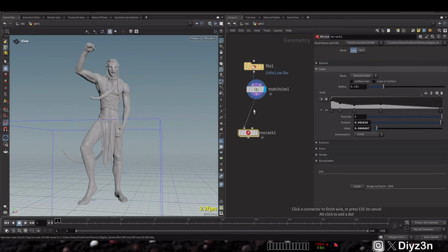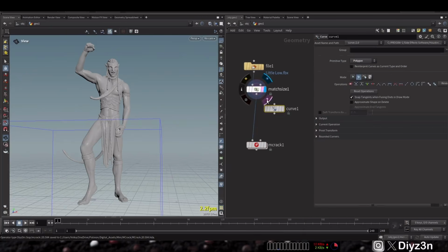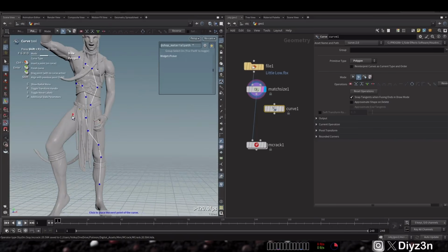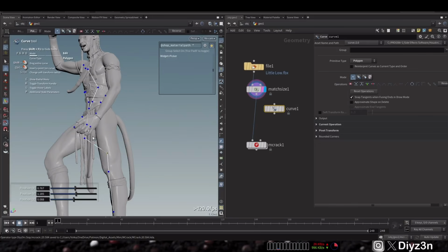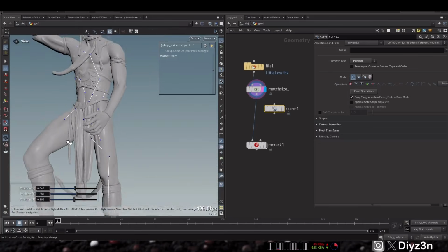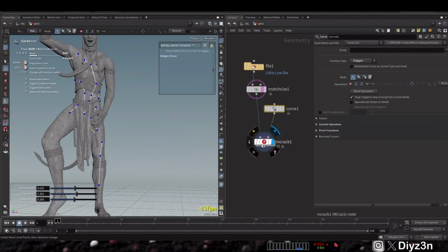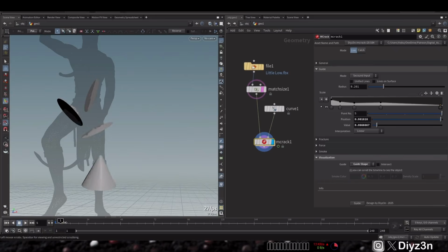And as you can see in the guide, first we need to specify the guide. It's set to the second input. Of course you can draw your curve here and you can have your guide, but make sure it's aligned with the geometry. It doesn't have any distance from it, and you can connect that to the second input. This is your guide for a crack, and this is simple. You can go to visualization and we have something called guide shape, and you can scroll to see that.